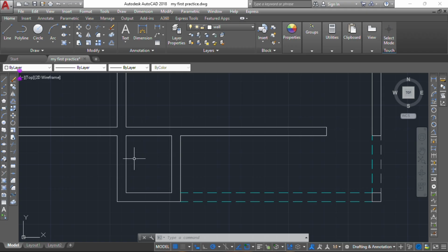but we need to consider some other things also, like the positioning of the water closet, right? Let's assume our water closet is here now. Let's assume it is here and we are fixing a door either here or here. Let's assume there is somebody inside here using the toilet and maybe the door is not locked from inside. Anybody coming inside without the knowledge that somebody is there can just open the door and see the person directly. So now if our door is being placed here, then we can go ahead and place our water closet here. At least anybody entering, we will not be directly seeing the person using the toilet. The person using the toilet is still hidden by this side here, right?